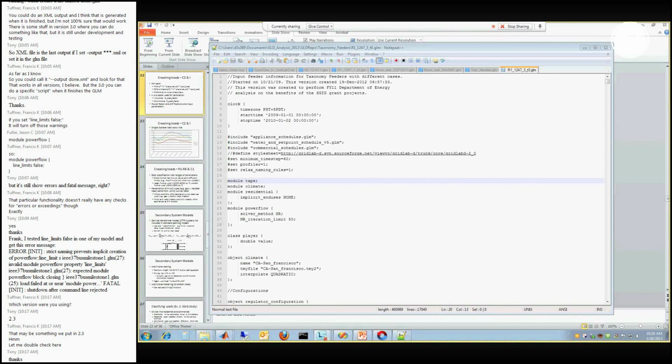The goal for this year is we're trying to add in some of the line charging and transformer charging type dynamics. So if you're doing restoration type work, that's what we're looking at. And the other one is getting some more detailed dynamic level models, transient level stability for inverters. So if you wanted to do rapid cloud transients or something like that, we could look into that. I don't know if we're really going to get in anything specific to fault type scenarios. I know we won't get to coordinated protection schemes or anything like that, as Jason mentioned, but we might get some simplistic fault inclusion.